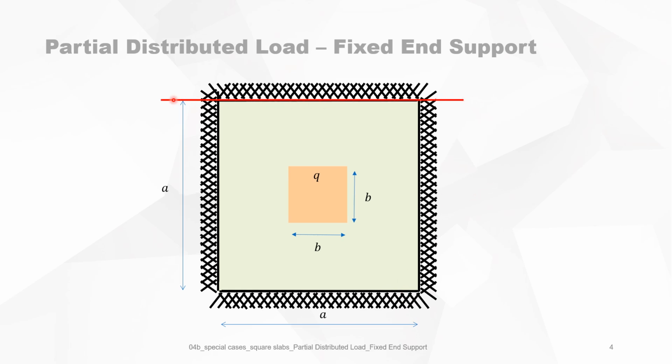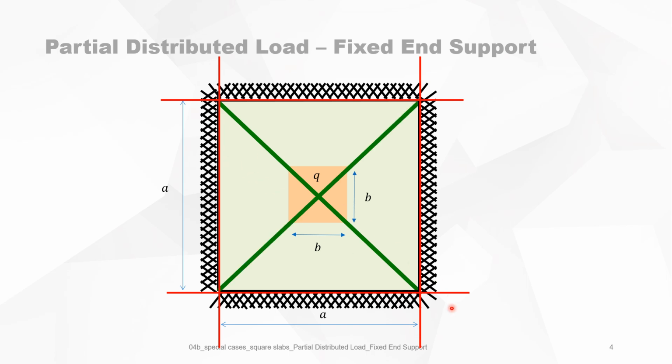First, we look at the axis of rotation. So at the four supports, we have the four axes of rotation, and the yield lines are between the crosses, or the intersections, of the axes of rotation. So we have from this to there and on the other side, but we have also, because it's a fixed end support, a plastic bending moment on top of the slab, which is on the four sides. So we have also there the yield lines.